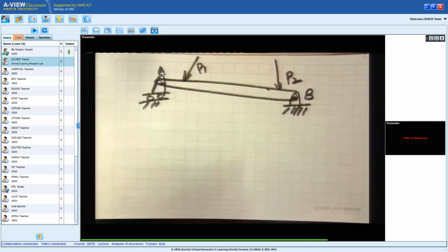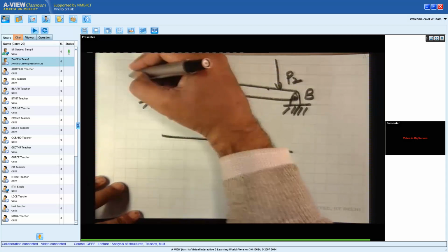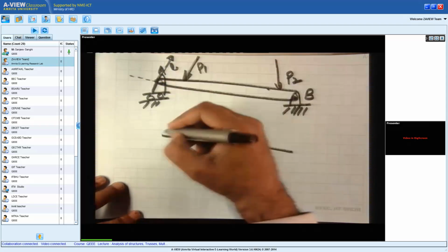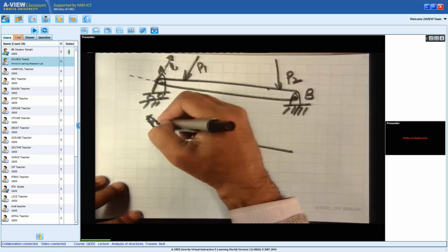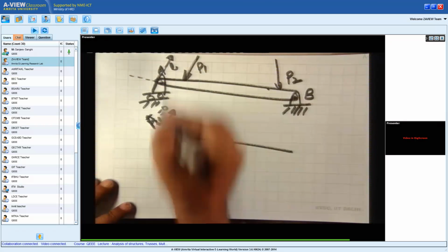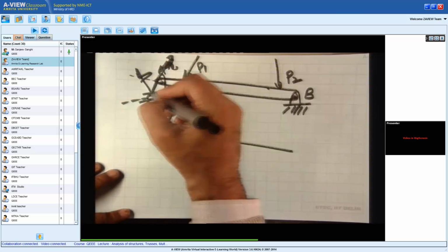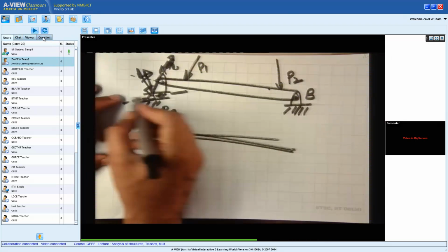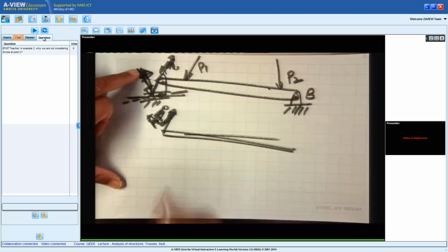Now clearly, if I draw the free body diagram of AB, at A I will get a force along this direction, perpendicular to the motion. It should be perpendicular to the motion of the rollers. So this force, let me draw it again. The rollers are moving, so we have to go perpendicular to the motion of the roller. The force in that direction is 0.